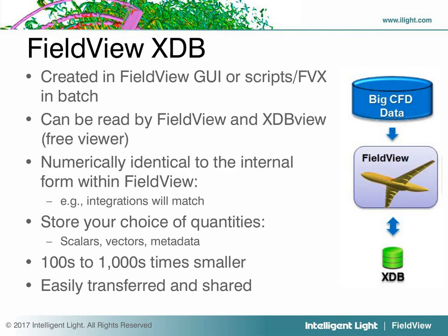So FieldView XDB files can be created from the user interface in FieldView, or you can also create these in batch using our FieldView scripting language, or FVX. As mentioned, these surfaces or extracts can be read by FieldView or by the free viewer XDB view that you can download from our website. These surfaces are numerically identical to what's internal to FieldView, so that if you're integrating on the surface from an extract or a surface that you created within FieldView, the integrations would match.